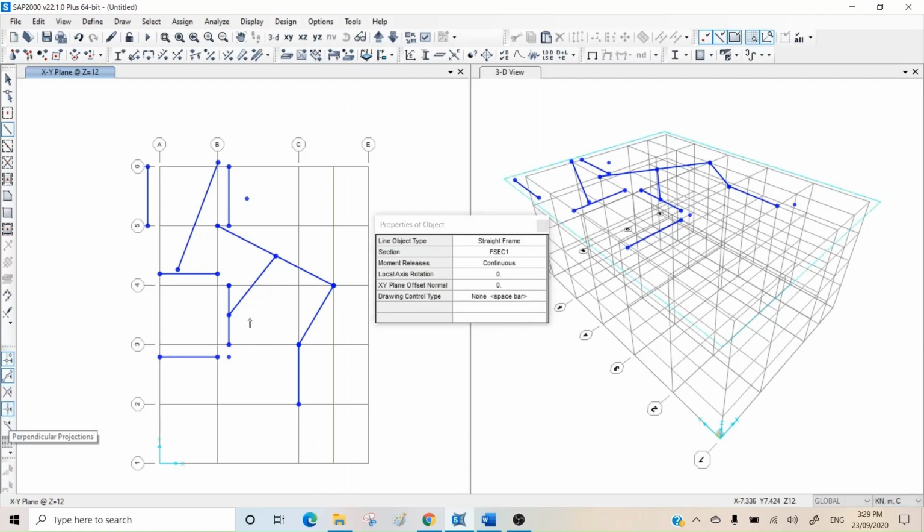If I choose perpendicular, guys, this is being recorded but somehow is live, so some minor mistakes you can see. Please accept my apologies, but let's move on. So this is a perpendicular. So coming from here to here, it's automatically connected to this frame. Or from here to here is mid, but when I move it, it is perpendicular. So different snaps are active. If some snaps are very close and you don't want them, while you are here, you can deactivate them. For example, you don't want to have perpendicular. Before clicking and selecting your second joint, you can come here and remove perpendicular.